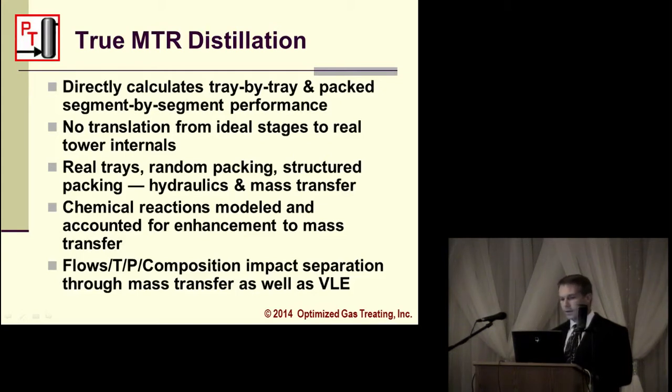One affects the other. In ProTreat, we also take into account the chemical reactions and ionic speciation that are happening in the solvents as they pick up acid gases or react with heat stable salts or alkali contaminants. And the reactions enhance, in some cases, the mass transfer that can happen.